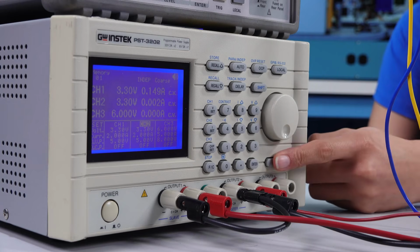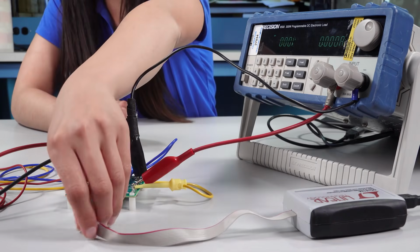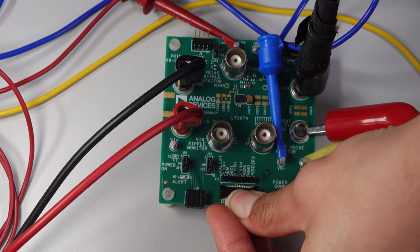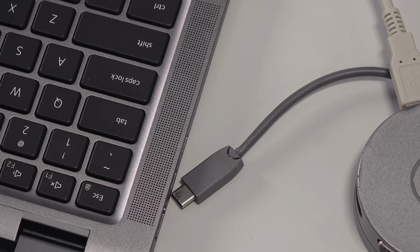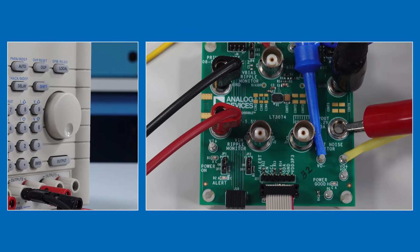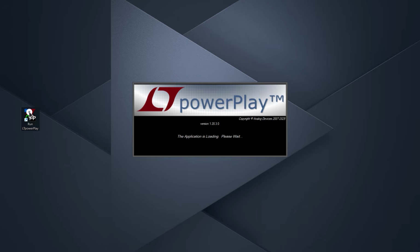Before we connect the PMBus dongle, don't forget to turn off the eval board power supplies and load. Now you can attach the ribbon cable onto pin J12 of the board and plug the USB cable into your PC. I'm using a USB adapter here. As we return power to the board, we see the same behavior as before, with the LEDs lit and the LT3074 LDO successfully regulating. Now let's open LTpowerPlay.